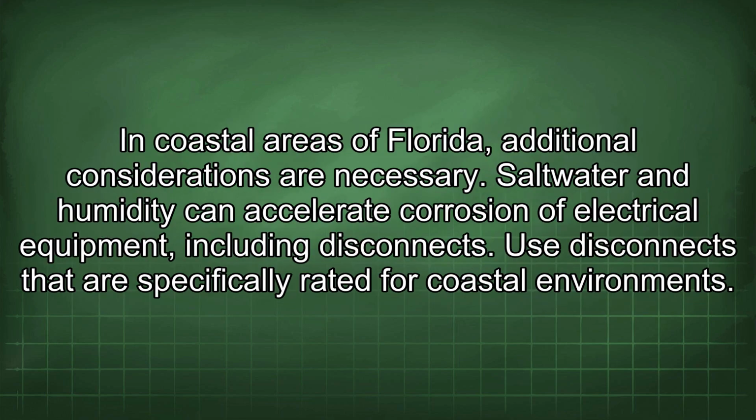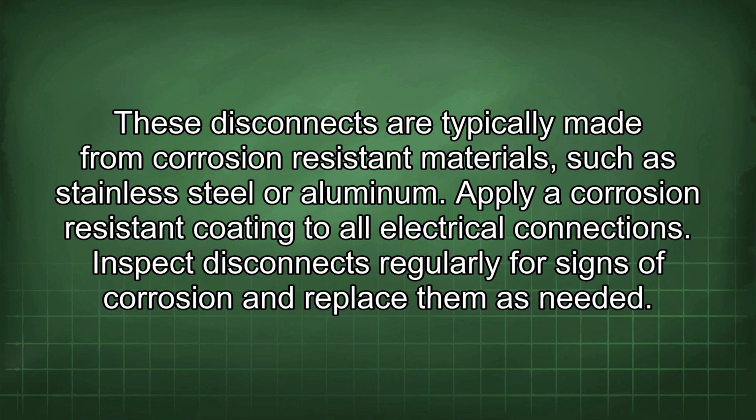In coastal areas of Florida, additional considerations are necessary. Saltwater and humidity can accelerate corrosion of electrical equipment, including disconnects. Use disconnects that are specifically rated for coastal environments. These disconnects are typically made from corrosion-resistant materials, such as stainless steel or aluminum.